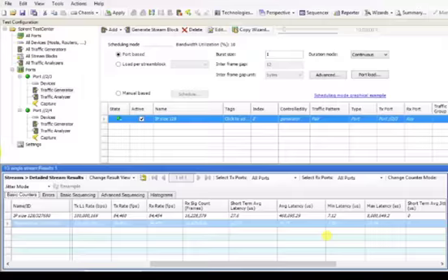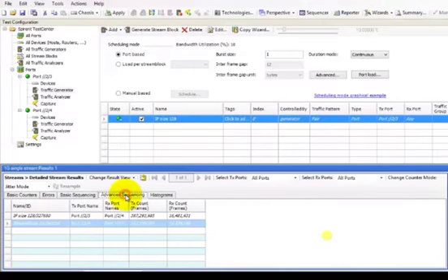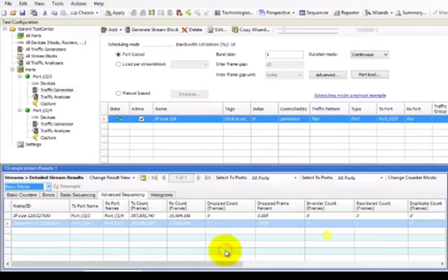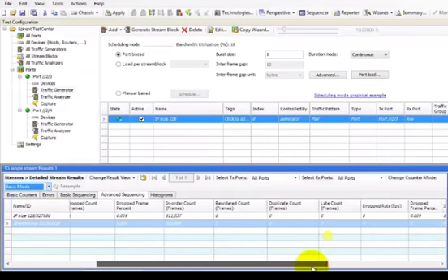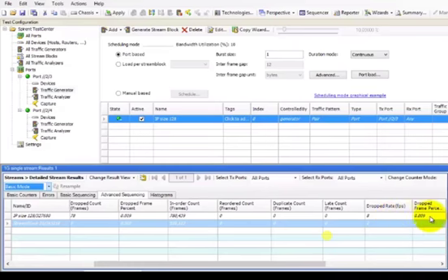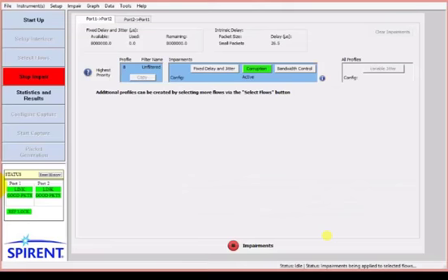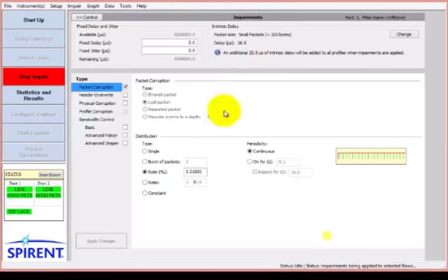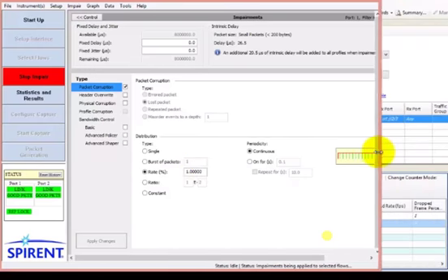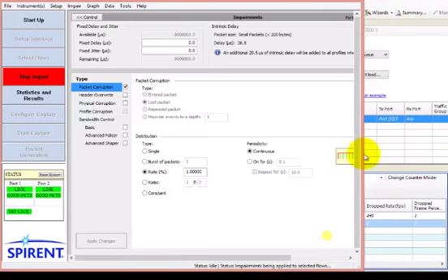And again, if we look back at the test center GUI and look at our counters that allow us to look for dropped packets and look for that 0.01% dropped frame percentage, we'll see that it's reporting 0.01% as we've set up on the Attero. So let's try a few different values of corruptions. Let's change that value to something a bit higher. Let's try 1% dropped packets. And look at the impact on the test center, counting up to 1% dropped frames.